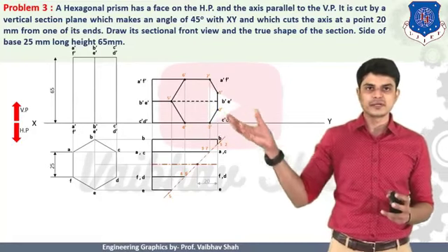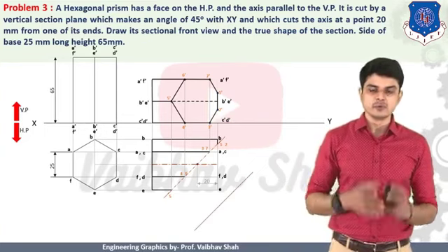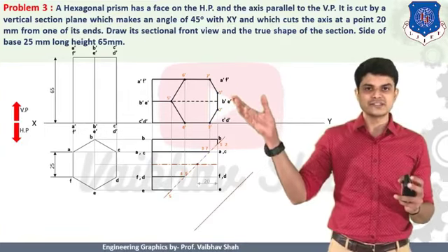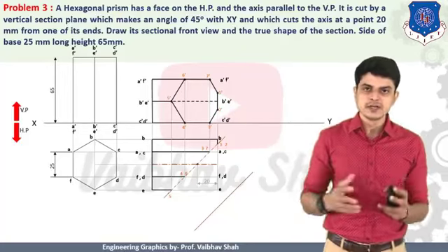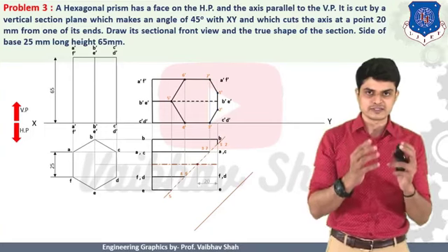After that, you should give the section lines in this plane. So this is nothing but your final view generated, and this is nothing but your sectional front view, because the section is seen in the front view itself, right? So now let us find out the true shape of section. So what we should do? Let us follow the process step by step.